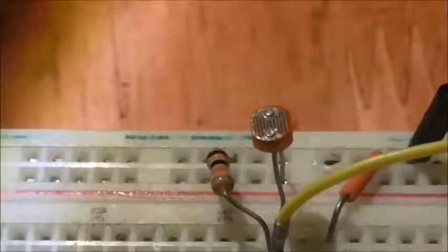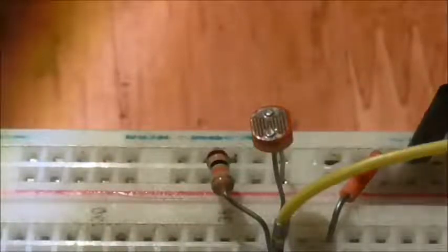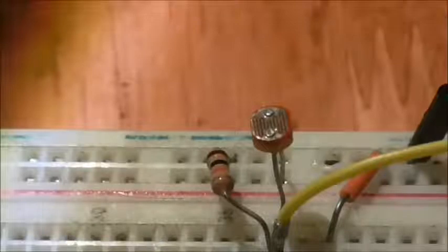Usually you'll find that they'll go from tens of ohms to several megohms, and they can vary even within the same batch. Now they're made with a semiconductor base, but there's cadmium sulfide in there as well for doping. So they're not really nice things, and they are made of quite hazardous substances.